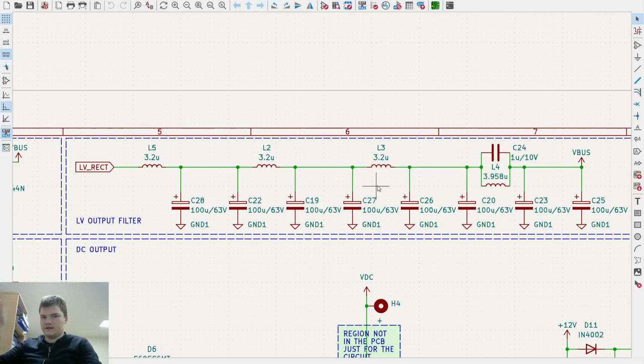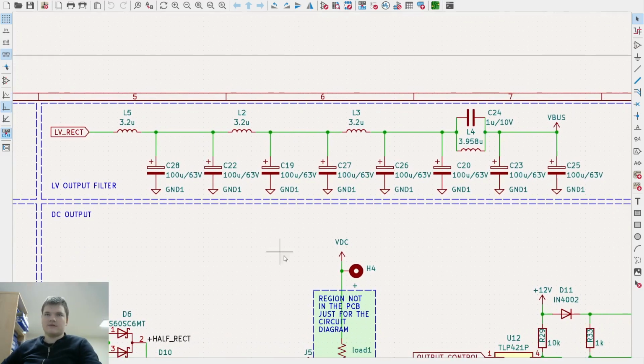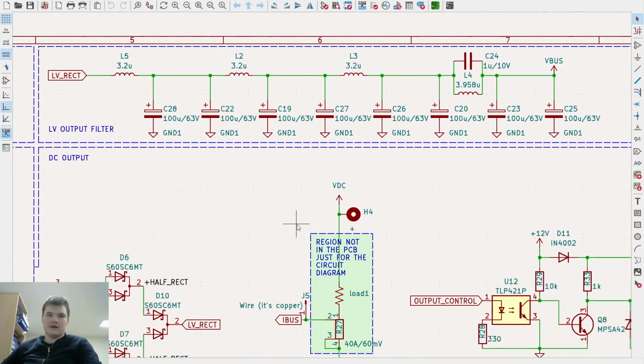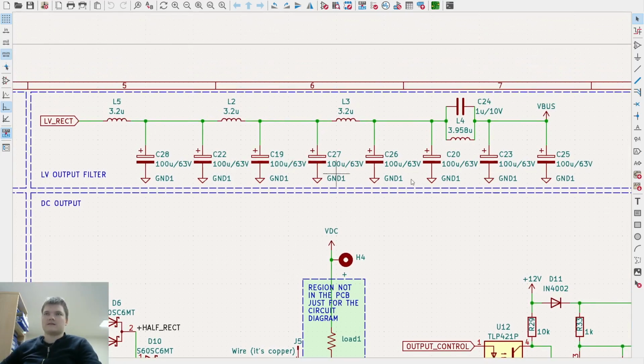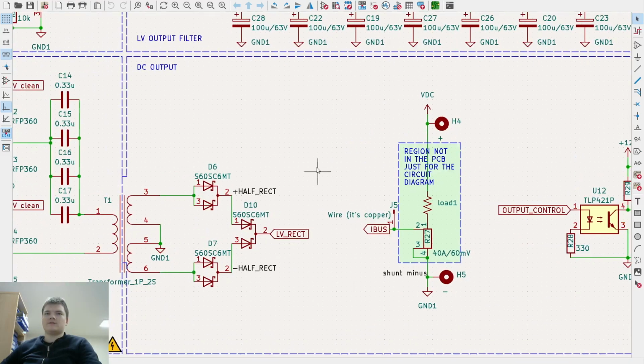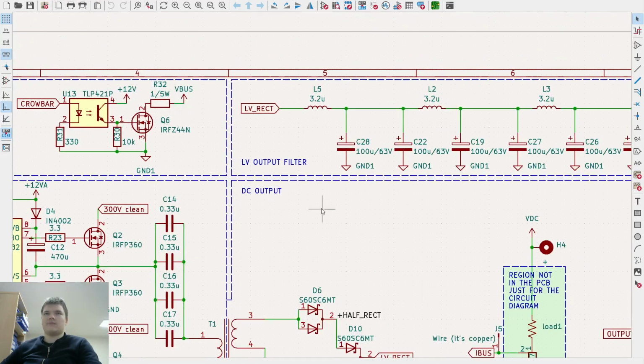So now you have an issue, because those capacitors are loaded to 20 volts, and they are not just going to suddenly lose all their voltage. You cannot plug the 12 volt device, because it will get suddenly a short moment, and yet a dangerous one, when it can just get too high of a voltage. So that's another thing that the crowbar does.